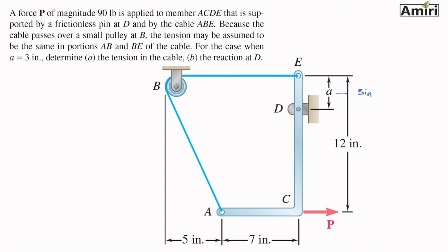All right, so this is a rigid body. Because there are multiple supports, a cable applied at different locations, and force P is at a different location, we cannot ignore the size. The forces don't go through a single point. So this will be a rigid body equilibrium problem.